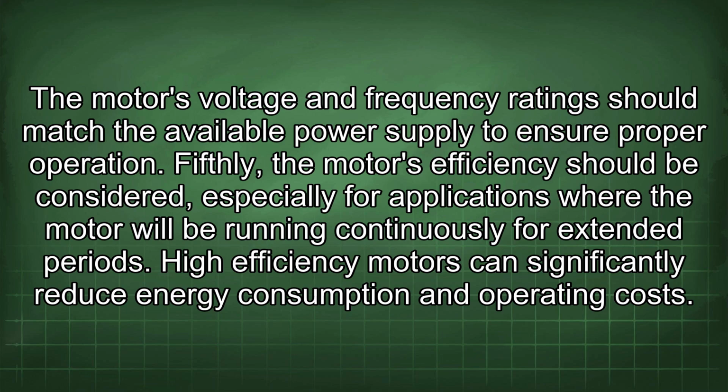The motor's voltage and frequency ratings should match the available power supply to ensure proper operation. Fifthly, the motor's efficiency should be considered, especially for applications where the motor will be running continuously for extended periods. High-efficiency motors can significantly reduce energy consumption and operating costs.